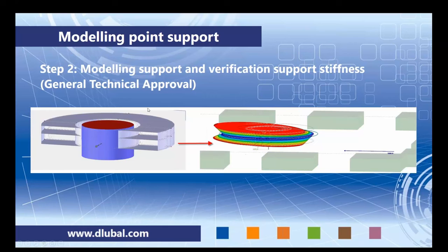So the point support consists of this bolt in the middle, two rigid surfaces on the top and on the bottom, and the glass pane in the middle, and two contact solids between these surfaces, transferring pressure and failing under tension. From defined loading and a deformation, a spring constant can be calculated.